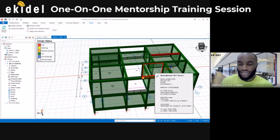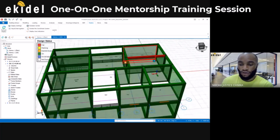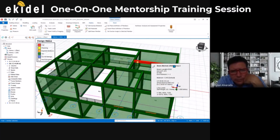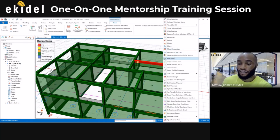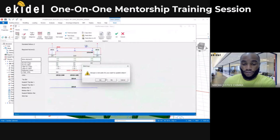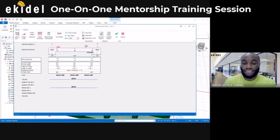Okay. But let me start with this one that's failing here. I'll right click here and then come and click here, section design. I'll click on this now and wait for it to open up. Now I just say yes, update. Now it's failing based on depth. They are saying that based on code, the minimum depth here should be 344, let's say 350, right? But we are using 300.